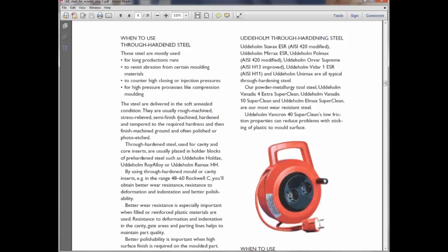On a small plate, a 1 or 2 mm bend will not matter. But on a big die plate, a small bend or small deflection can be a big variation. That's why we always try to remove that bend, that deflection, after the heat treatment process.